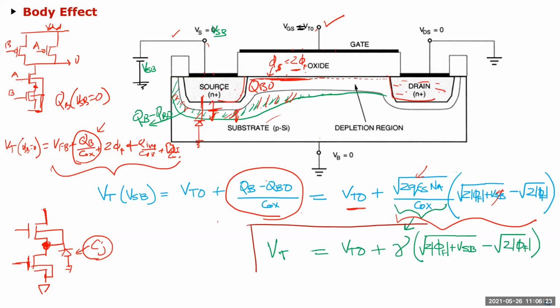That's why when we talk about MOS modeling tomorrow, we'll see that level 1 uses this, but when you get to level 2, 3, and all the complicated BSIM4 models, then it starts changing. And we derived the equations for this because we already derived the equation for how much charge is needed for a given voltage, so we use that equation here. Obviously, all that is assuming it's homogeneous, purely square, and all that. You can see these are all very regular shapes.